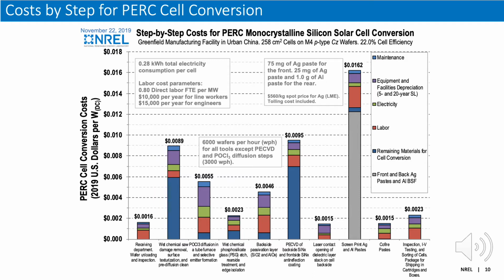So here I want to pivot back to discussing yield again. When the wafers are scanned at the beginning of this process, around 0.1% are rejected for quality purposes, and there is a similar rejection rate through each step of the rest of the process. So by the end of the process, about 1% of wafers or cells are ultimately rejected. Again, to go back to our 100 number from the wafer yield discussion, if you need 100 cells, you actually need to aim to produce 101 cells.